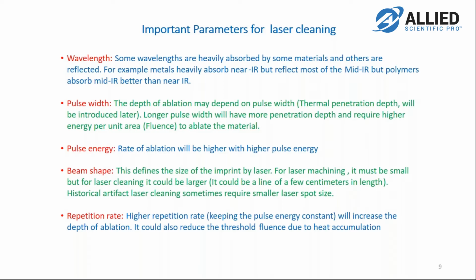The beam shape, depending on what you're cleaning. Sometimes you're cleaning artifacts or historical structures that have a lot of details, so you need to use a small beam to be able to get to all the nooks and crannies. If you are cleaning a wall, for example, with no features, it may be better to use a linear beam with larger lengths.